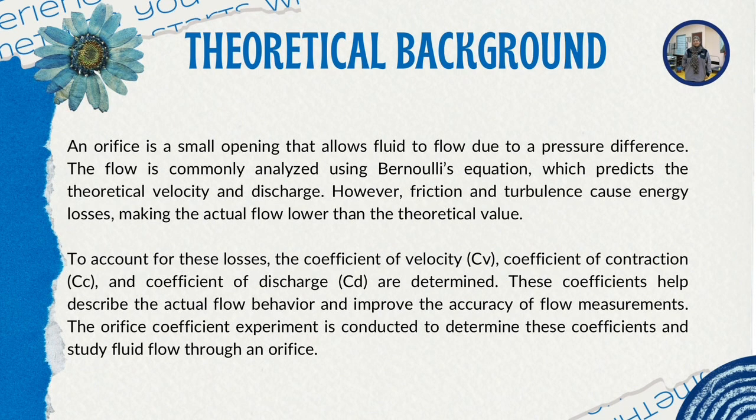To account for these losses, the coefficient of velocity Cv, coefficient of contraction Cc, and coefficient of discharge Cd are determined. These coefficients help describe the actual flow behavior and improve the accuracy of flow measurements. The orifice coefficient experiment is conducted to determine these coefficients and study fluid flow through an orifice.